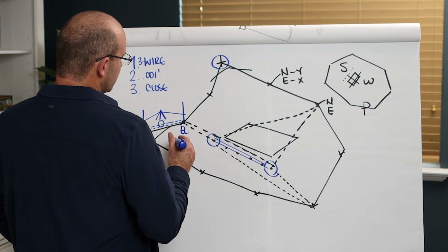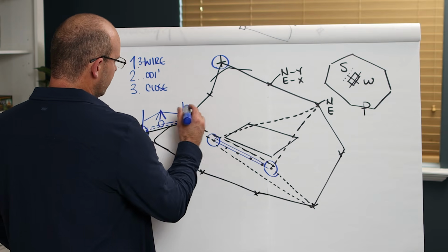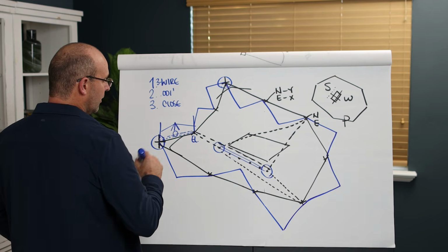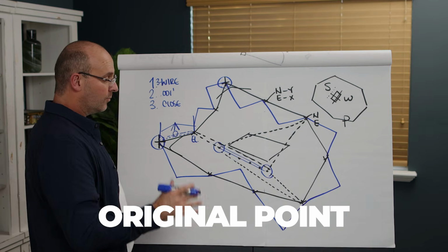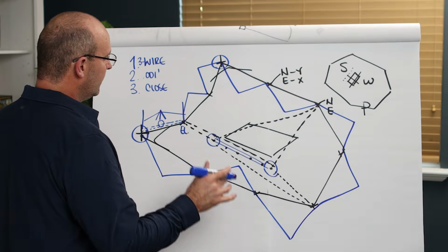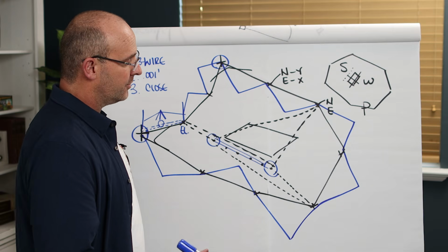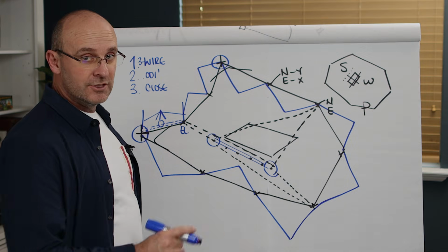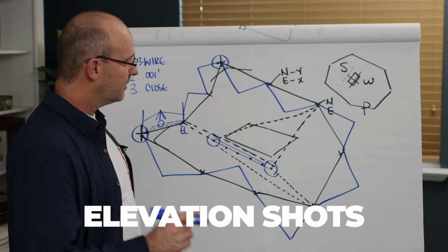And so let me make this point that you will backsight, foresight, all the way to your original point. And what will happen is that you will, in a nice format in your field book, log each of your elevation shots.